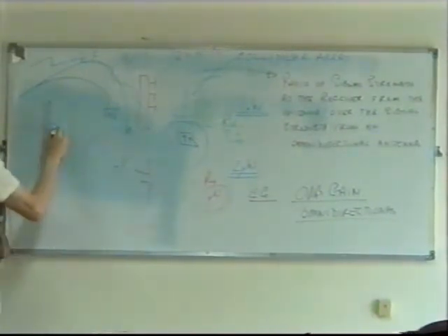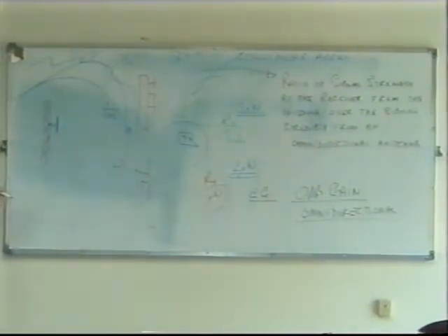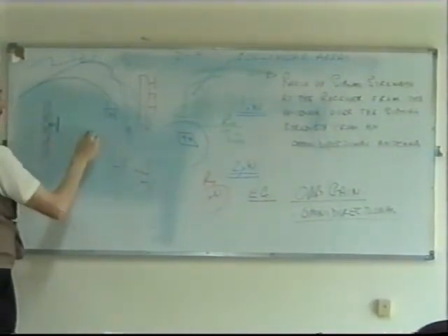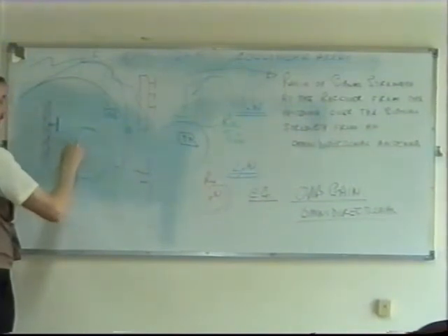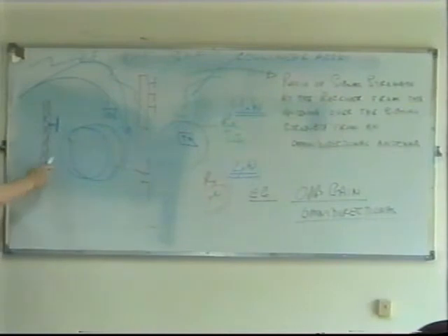Say I have a dipole mounted at the side of a large mast. Now this mast is made of metal, and so therefore the mast itself can behave a little bit like a passive element. Although we talk about dipoles, and I've come out with all this fancy theory, in practice, if I have a dipole at the side of a mast like that, and I want that to be omnidirectional, it probably is not going to be fully omnidirectional. Because of this mast acting a little bit like a director or reflector, depending on the distance, I might actually find, if I was to take the polar diagram of that, instead of getting it nice and circular, I might end up with something like this. Right, not quite circular. It's still not too bad in this direction, but it does affect it.